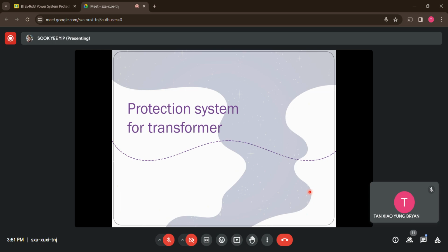Then we also talked about the non-true fault situation for a transformer, which is inrush currents, which we need to take note of whenever we are choosing the protection scheme for the transformer. Why? Because the high inrush current is considered a natural effect for the transformer when you start its operation, as the transformer is trying to compensate for the residual flux within the transformer core.